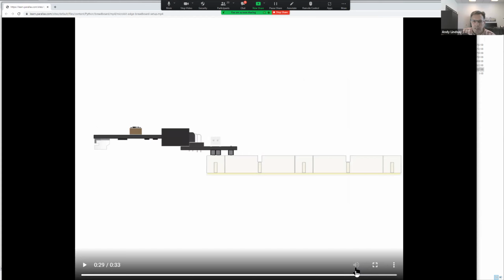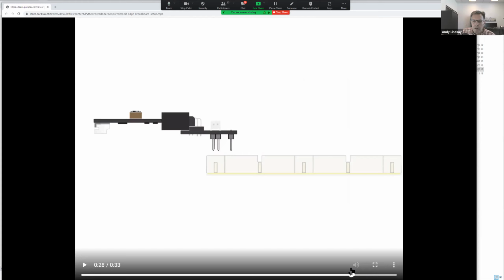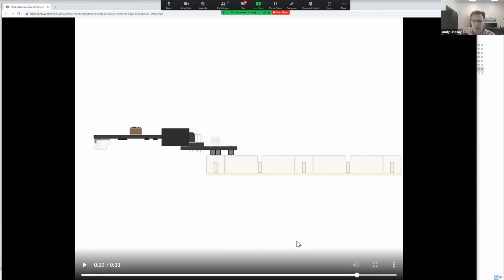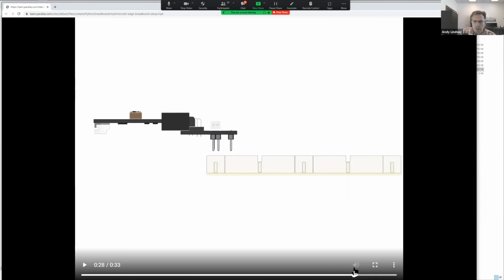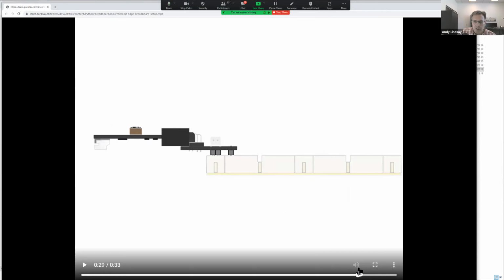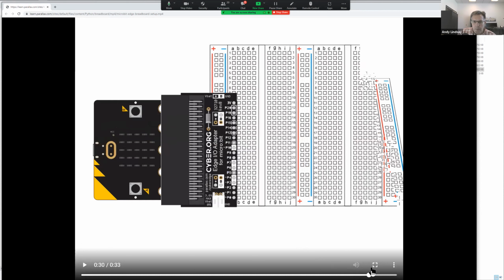So we show that these pins sink all the way in until the little plastic headers that hold the pins together are up against the breadboard. So make sure, everybody, once you've got your pins aligned, to press all the way down until the edge adapter meets the breadboard.